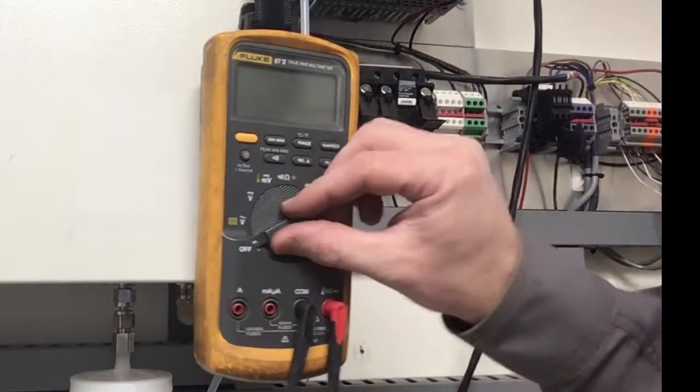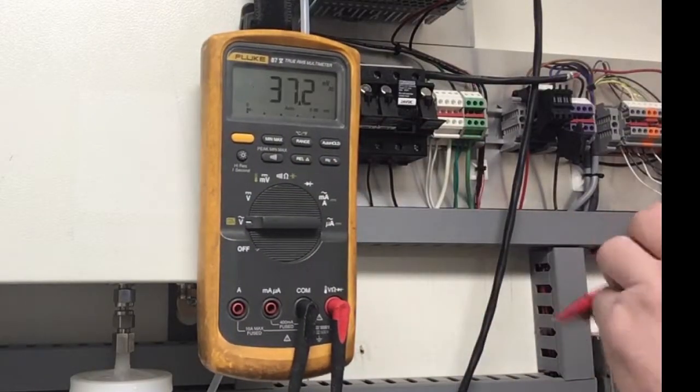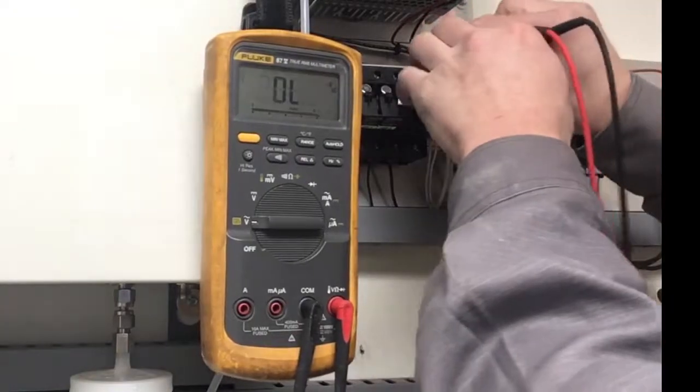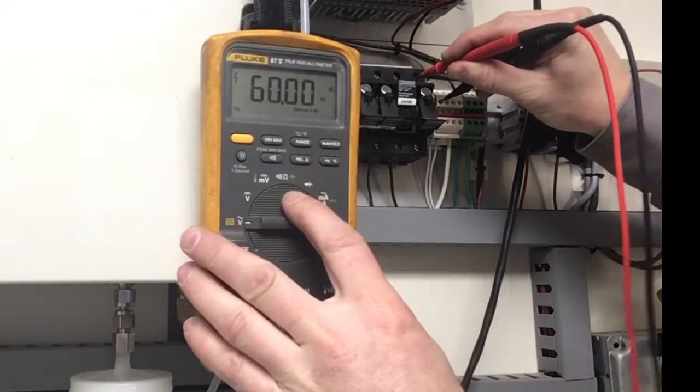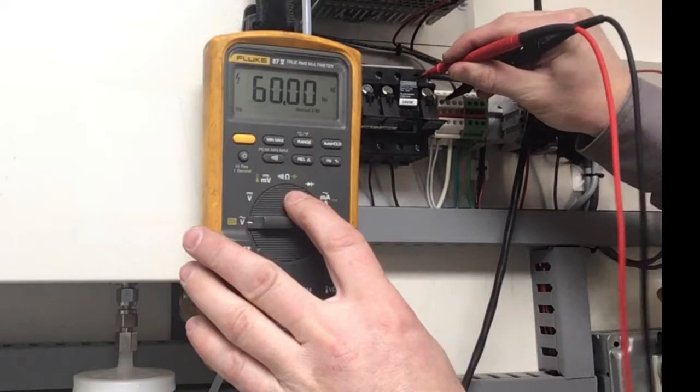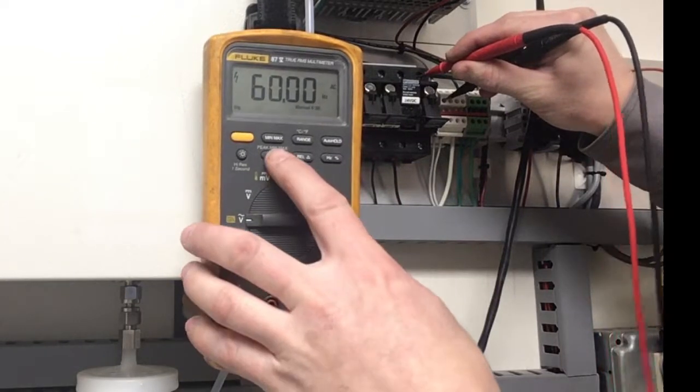Frequency measurements can be taken during any measurement except for the diode test function. To activate the frequency counter, press the button Hz%. This displays the number of times the signal crosses a specific trigger threshold in a second of time. The trigger point can be adjusted from positive to negative by using the tone button.